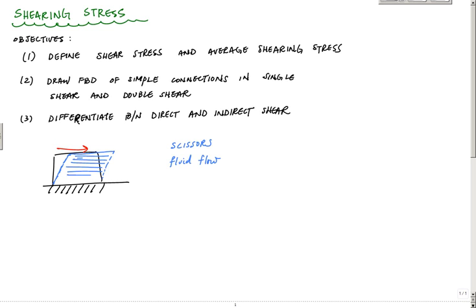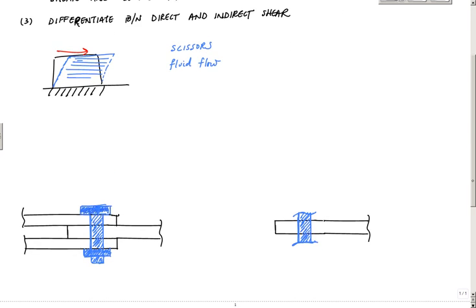But the thing I think of here, let's take an example. Let's take a connection here. So here I pre-drew, if you can imagine, a bolted connection with two plates here, or one, two, three plates here, and then let's say I have some force. I'll call that P here. And if this whole thing, this connection, is in equilibrium, I know that each of these forces here is going to be P over 2, on this plate right here.